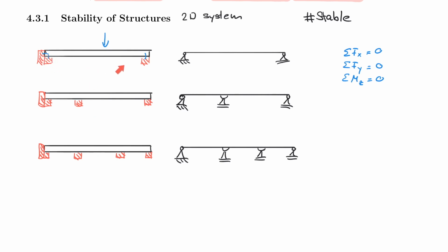So this would just start to bow down, whereas this one here would bow down here, and then here you would actually have an uplift, if you will, or like an upwards bending. We talk about bending much later, but you understand that this support here changes how this entire structural system responds. And the same is true here. So this support here now adds some different behavior. And so engineers really have to define that, and engineers have to also know, hey, how do we think about this in terms of stability?